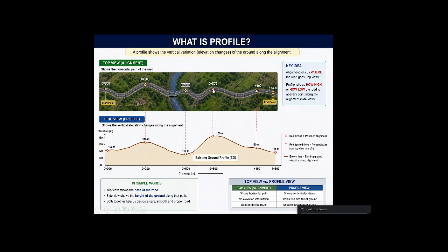As I change the alignment, as I change the shape of the alignment, at the same time, because of the dynamic view, in this profile view you see the difference, like before it was 160, and as we change the alignment line, we see the difference in alignment here also. So the line goes like this type, not like this. So this is the beauty of the profile view.